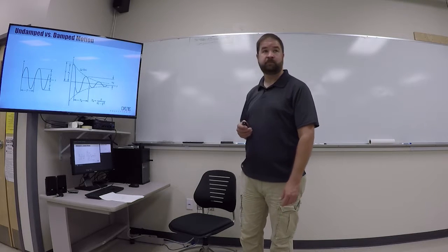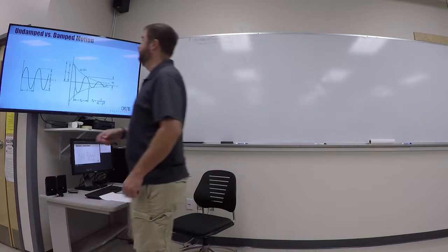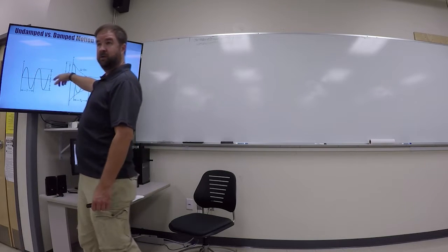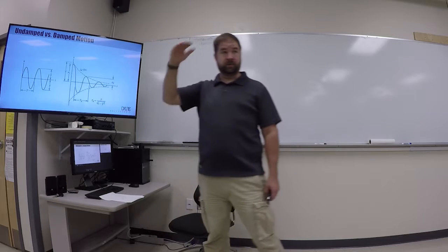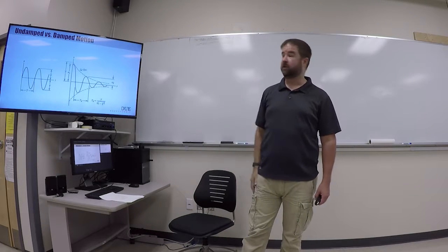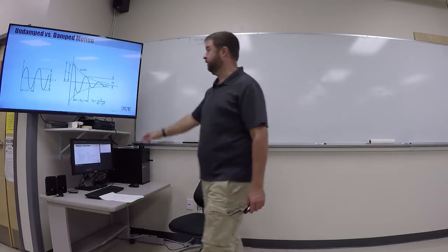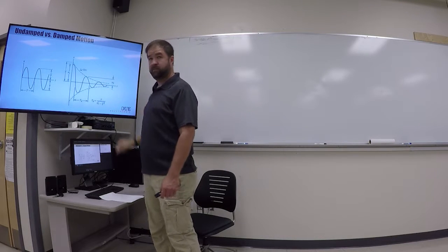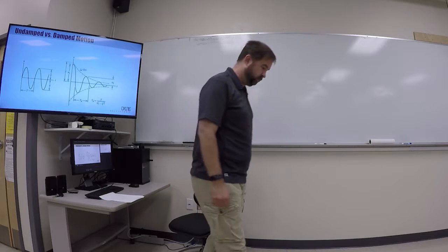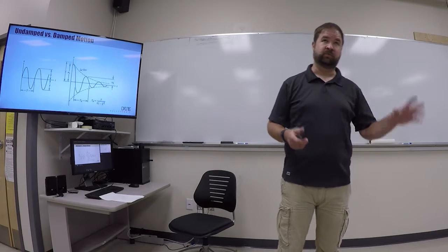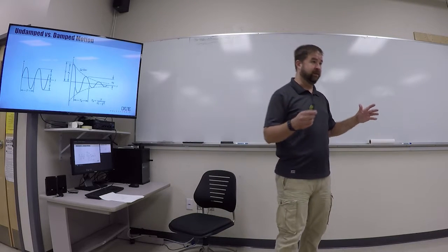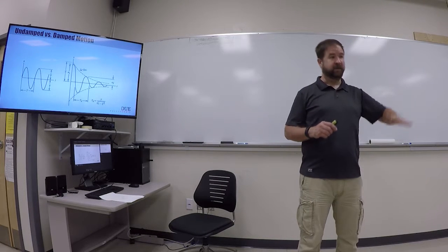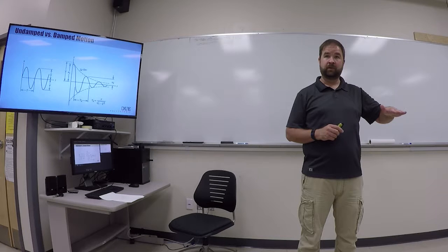Yeah, there we go. Okay, so spring mass system. If we input a force, it's going to respond to that force. And if the force continues on, it's going to keep oscillating forever. We put a damper on there, and the initial response might be large, but then it bounces out. If your shocks are properly working and installed on your vehicle, if you push down on the bumper, it should go down and come back up and pretty much stop.